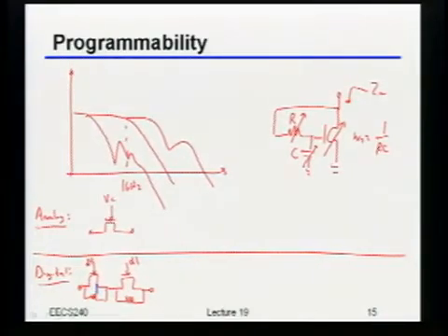So as an example, if I turned on D0, I would have half of the resistance. If I turned on D1, well, maybe it wouldn't exactly be half. It'd be whatever the series resistance of those two switches is. But at least if I do things right, I can set it up so that the ratios of resistors are reasonably well known. Okay? All right, so that's easy.